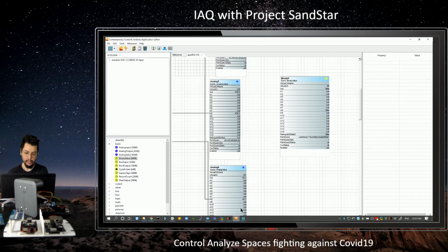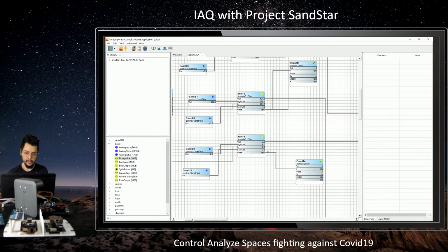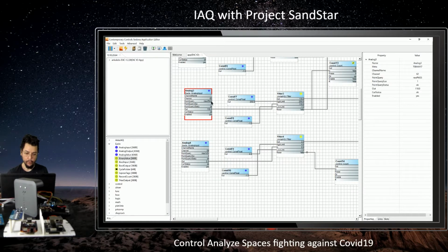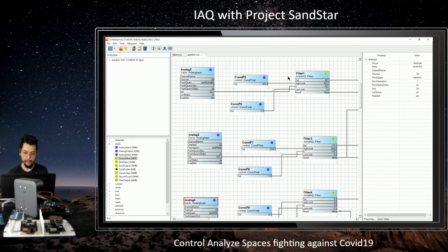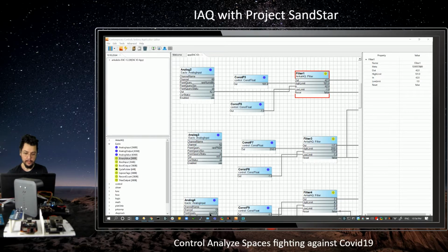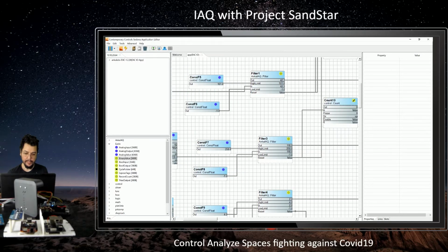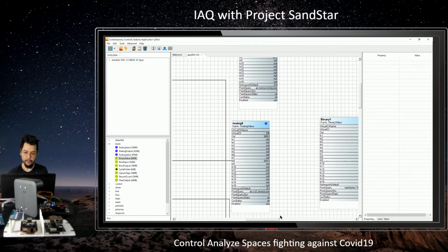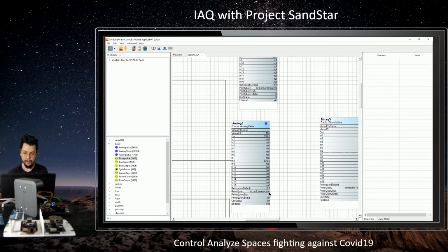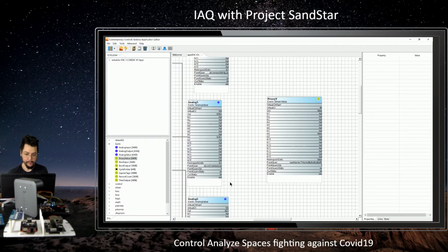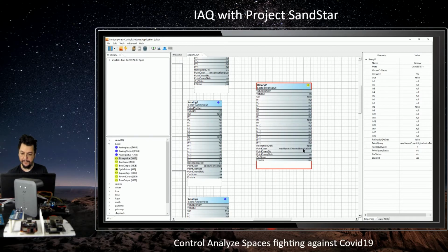If you want to look at the code in the Sedona layer, we have the readings for raw PM 2.5, raw VOC. This is the raw data. We are passing it to a filter for high and low resets, and then we pass it out to be read by the Haystack layer. We have the tags air, CO2, zone, and so on and so forth. So this is basically the virtual channel. We are creating the AV value. In here we have the defined humidity indicator.